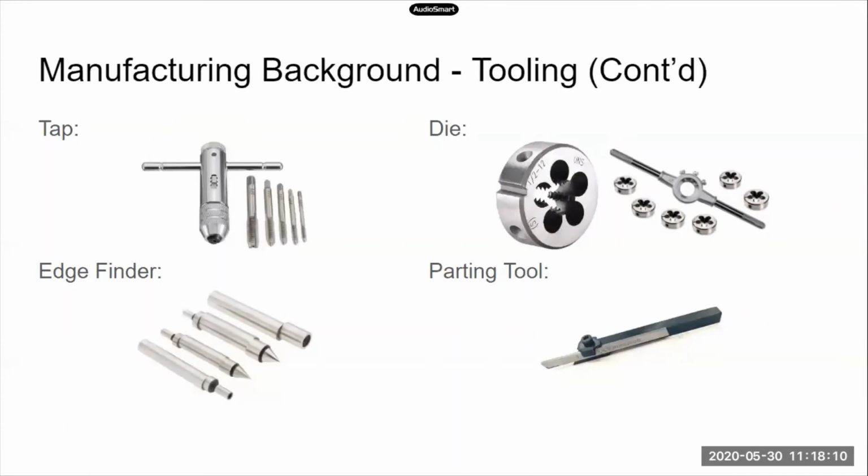Now, as far as screws or bolts, anything with that sort of edge, typically you'll use taps and dies. There are some other machining methods that you can take, especially on the lathe. There's a special tool head that you can go across the outside at a certain feed rate, and it will basically spin the thread of your bolt or screw onto that. Taps go internally to a hole, dies go externally.